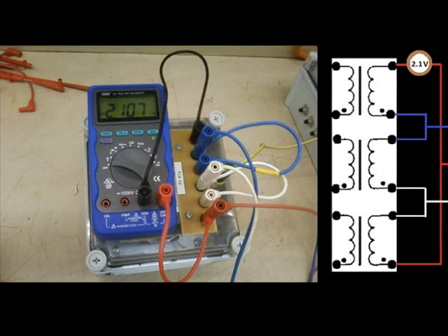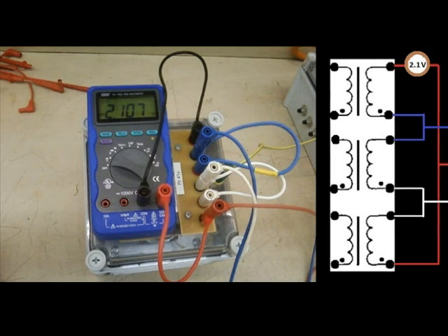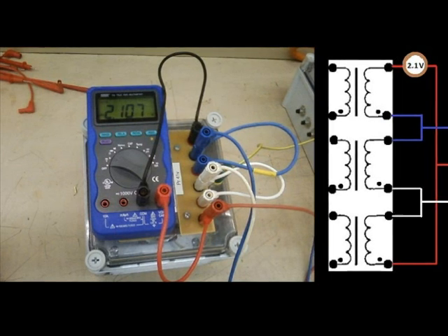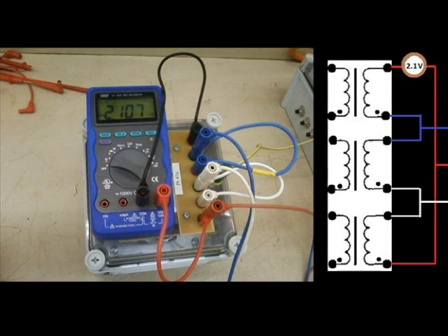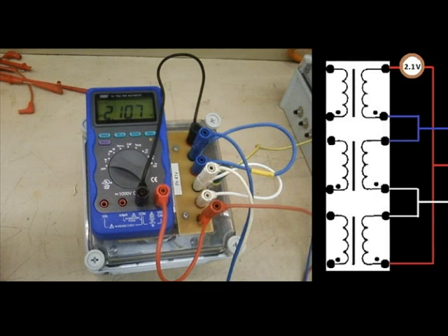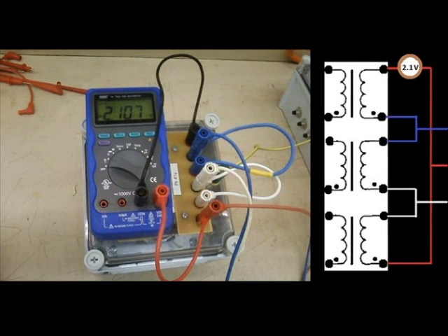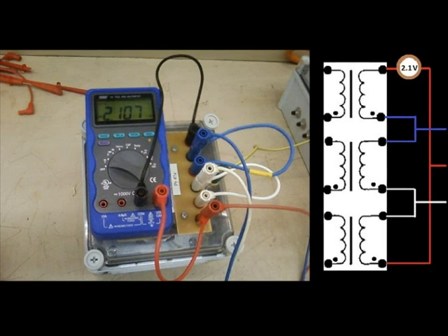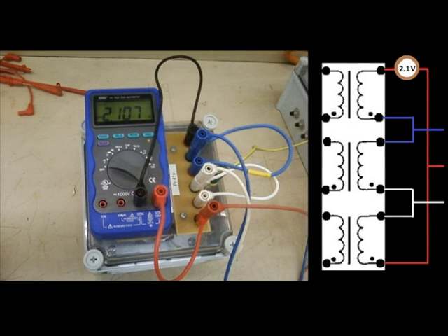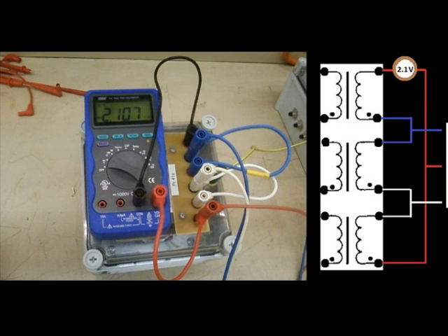We've connected the supply and energized, and we're finding that the voltage across that last connection is around 2 volts for this particular transformer. That's indicating to us that although there is a little imbalance there of a couple of volts, we do have the correct polarity as shown on the drawing on the right, where we can see we have dissimilar ends connected with the use of the dot notation.